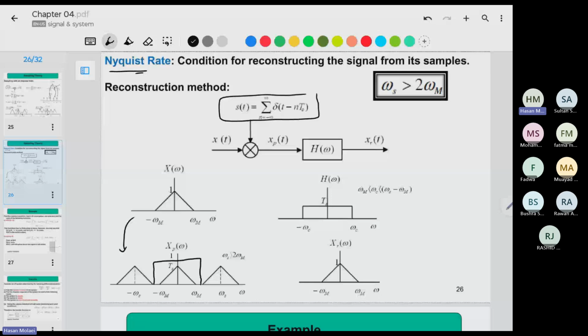you saw low pass, how we make low pass filters, yeah? The easiest way was an RC circuit, yeah? Right now, you find, yeah. If S is small, H would be 1.